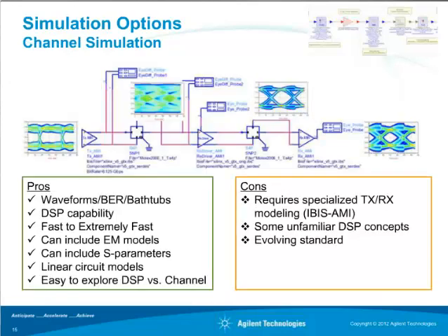Let's consider a third class, the one we're going to focus on here as an option for working with channels. So channel simulation, as the name implies, was designed and implemented specifically to look at a communications channel. As such, you can see that it has some very important pros here. We can look at waveforms, we can look at bit error rate, we can look at bathtubs, we can look at jitter, all of the kinds of metrics that you'd be associating with a communications channel.